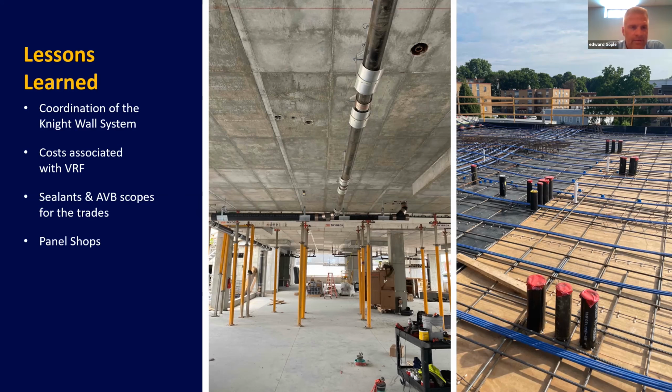And then, as the gentleman mentioned before, the panel shop drawings for us were huge on two sides. And then I think Aaron touched on it, trying to increase the spacing to 24 inches. Some structural engineers find it a challenge, but you just have to talk them through the process. And then also when the panel drawings come in, making sure they don't double, triple, quadruple the stud packing per se.